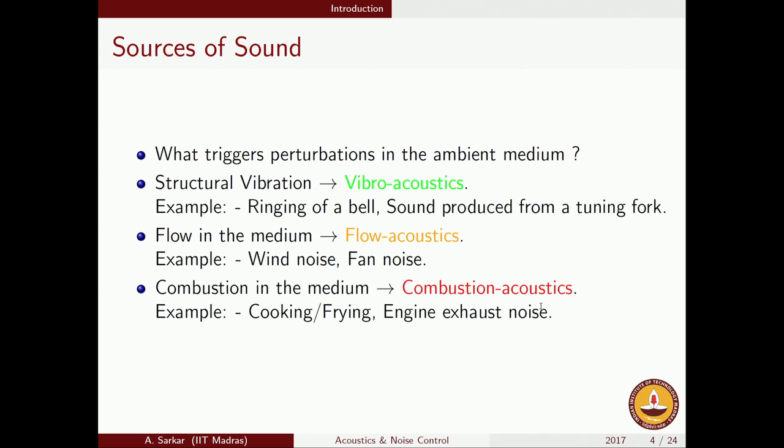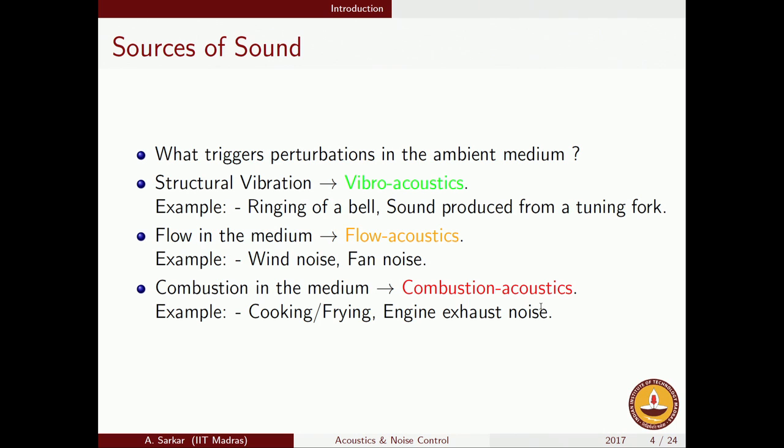That is true even if your cooking vessel does not vibrate. The cooking vessel, if you have noted, is fairly rigid. As the cooking process is going on, you hardly have any perception of vibration of the vessel. So, it is not because of the vibration of the vessel that the sound is happening. This is something you would have definitely seen as you or your mother was cooking in the kitchen. But believe it or not, the same thing is happening when your IC engine is undergoing a combustion process. Basically, it is hot oil which is getting sprayed within the combustion chamber, and the same crackling sound is obviously going to get generated due to the combustion process in the IC engine also.